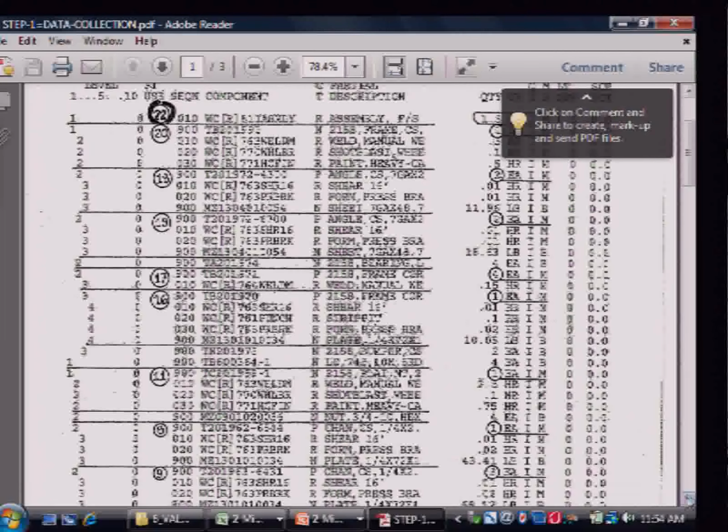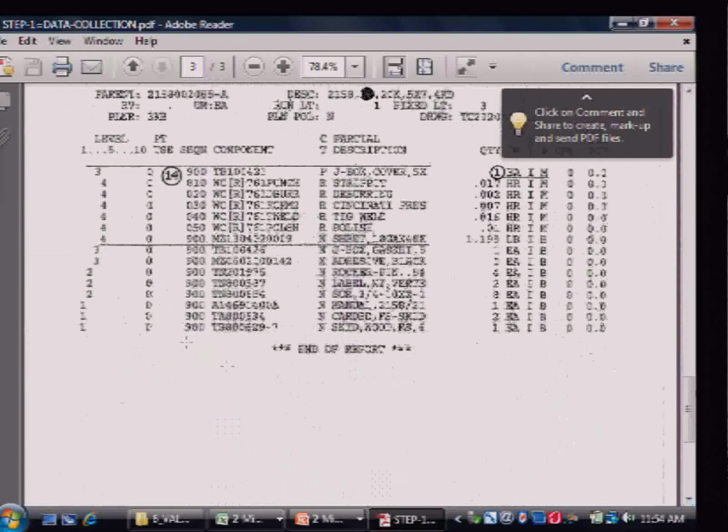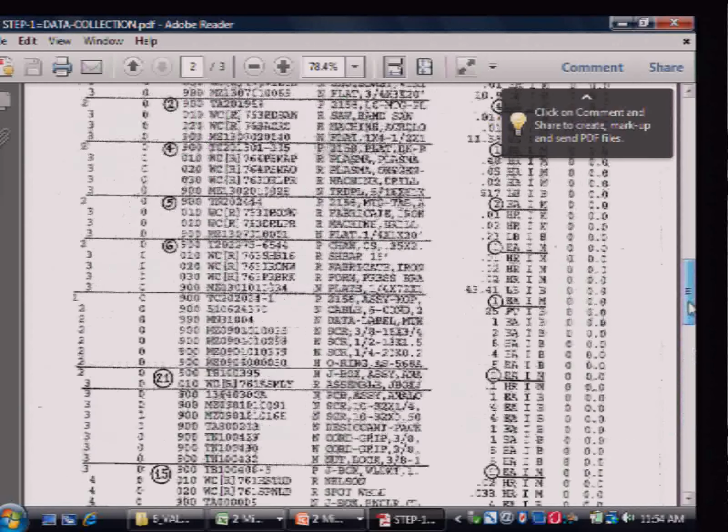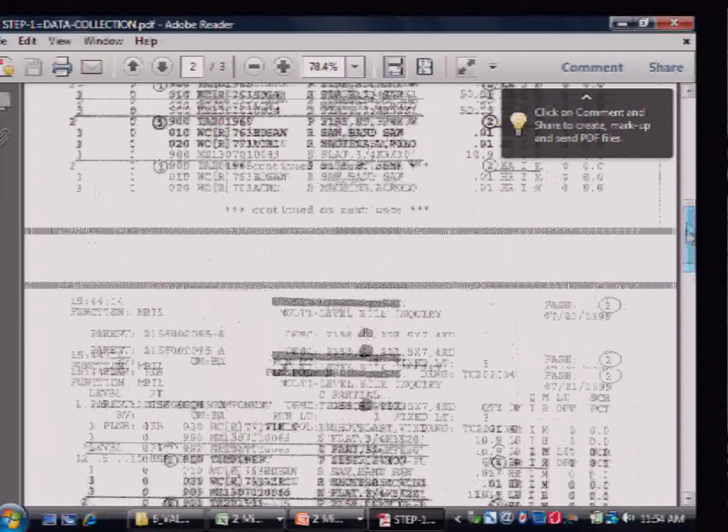If you go way down the structure, the indented bill of materials, these level 1 items, see this is the manual. You have to put the manual as far as assembly and operation of the scale. You have to have cardboard on the skid because that's what you're going to pay for, and you're going to make the customer pay for this item. Then you need wood to make the skid. So the level 1 items are what constitutes what goes directly on the truck, and then the level 2 items are internal to each level 1 item. And then the level 3 items are internal to the level 2 item. The level 4 items are internal to the level 3 item.